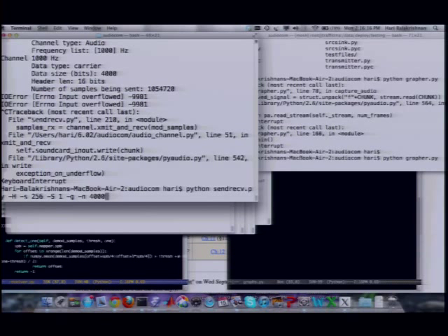In that command line, the dash little s256 refers to the number of samples per bit. I'll get to that point in a second. The dash capital S is the kind of source, something about the nature of the source. Capital S1 means that my entire information is sent as ones, which means I'm sending a pure sinusoidal carrier. All I'm doing is sending the sinusoidal carrier. Dash G just means show me some graphs, and N refers to the number of bits I wish to send. Okay? So these are all documented, and you don't have to worry about it.